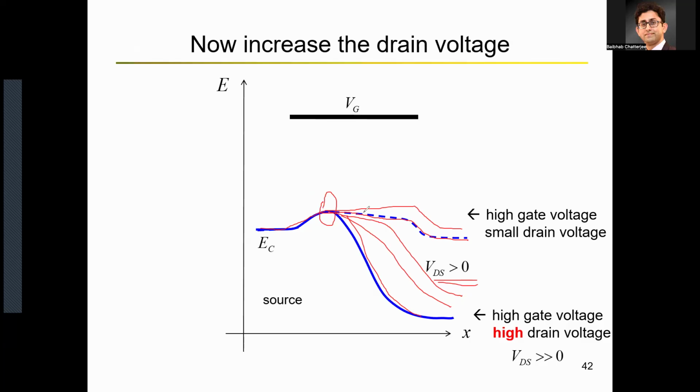What does that bump signify? Remember that originally you had this much height of the barrier. You applied a gate voltage, and even after applying a gate voltage, there remains a little bit of bump. So you still need to have a little bit of energy in those electrons to make sure that they roll up the bump, and then rolling down is not a problem at all. So what that signifies is that you still need a particular amount of threshold voltage for the electrons to pass from source to drain. Any MOSFET will have a threshold voltage, just like the diodes had a threshold voltage.